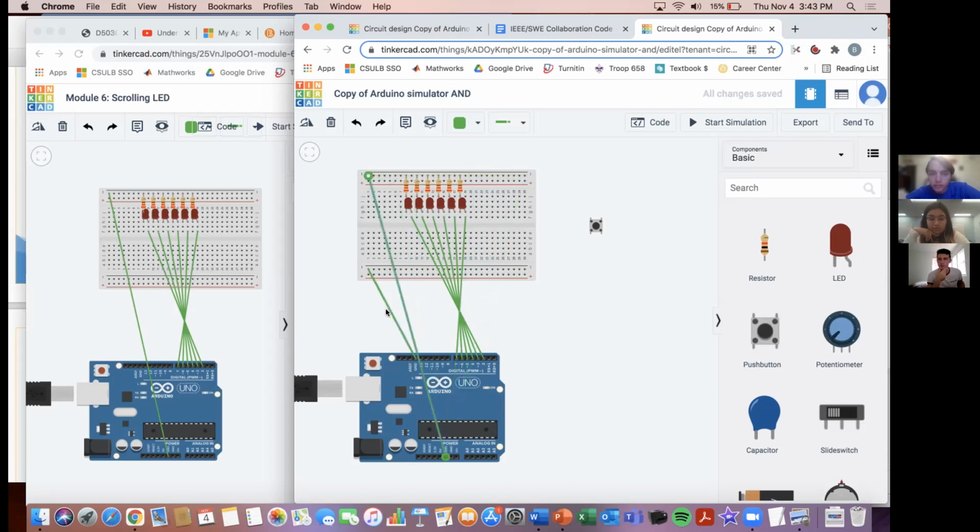Okay, I see. So the whole breadboard itself has two halves to it almost. Yes. So basically what you just need to know is the buses are connected all along their certain lines. The rows are all connected, and then these rows are connected to themselves. And then this bus is connected here and this bus is connected here. So you can think of this as one half and this as another half. Gotcha. That makes sense. Thank you.